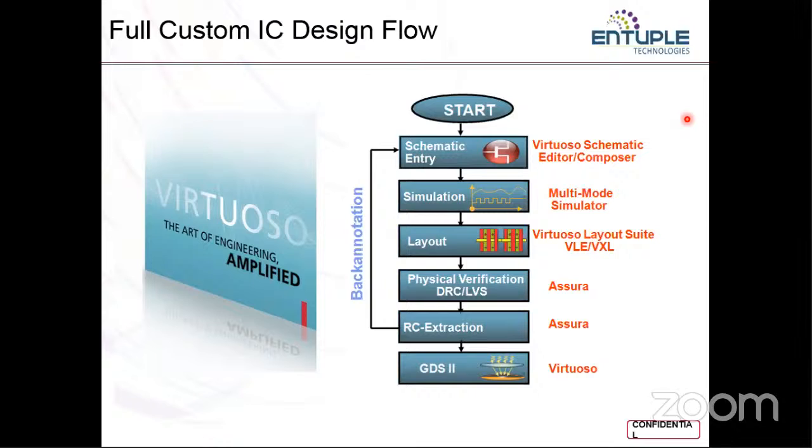So how is that indicated? By a parasitic resistor. Just imagine that you are trying to connect two different layers, like a metal layer with a polysilicon. So you need a via, which acts as a connector. Like you can imagine a plumber who is trying to connect two pipes of different diameters.